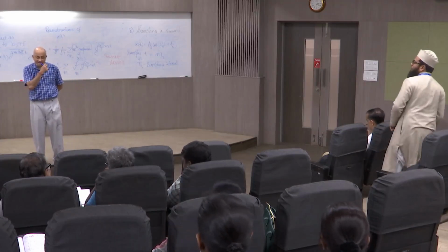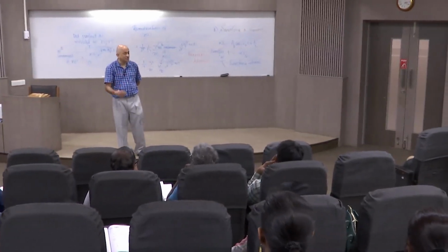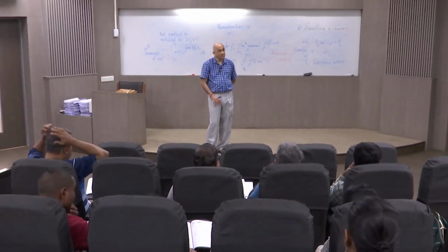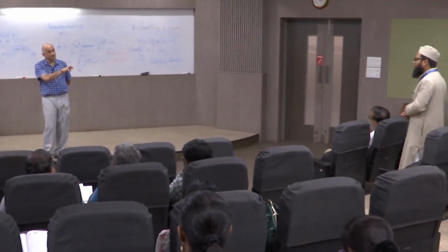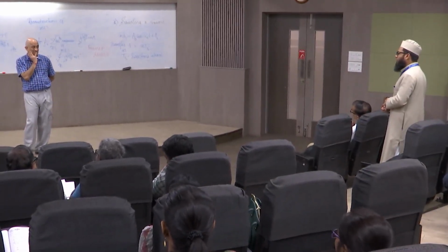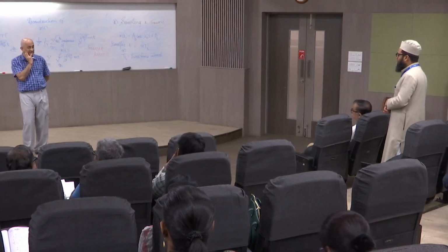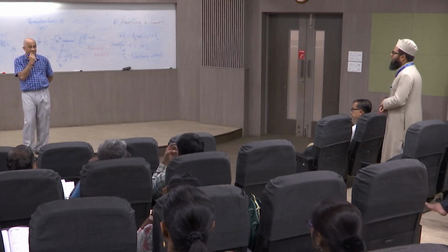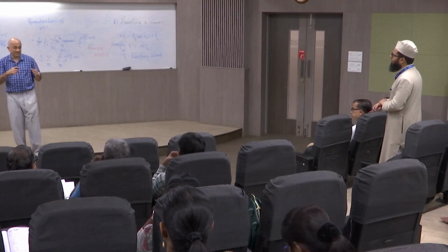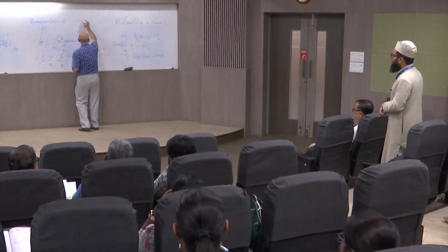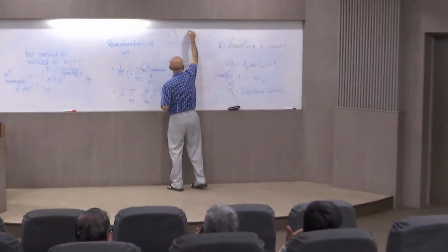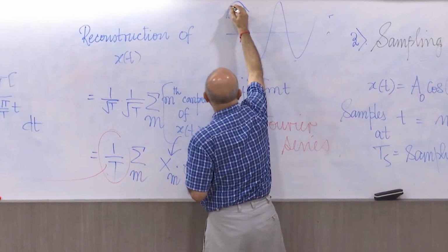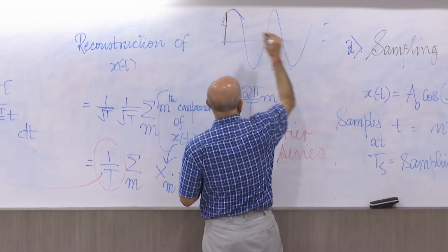Now, you have an analysis for it, isn't it? You have an analysis of why it should be twice the maximum frequency component: the aliasing effect. Now, have you thought about what happens to a single sinusoid when there is aliasing? When you sample a sinusoid, what does it do to the sinusoid? Let's look at it this way. You have this sine wave, and you don't quite keep this sine wave, but you keep very narrow pulses taken at intervals of Ts like this.